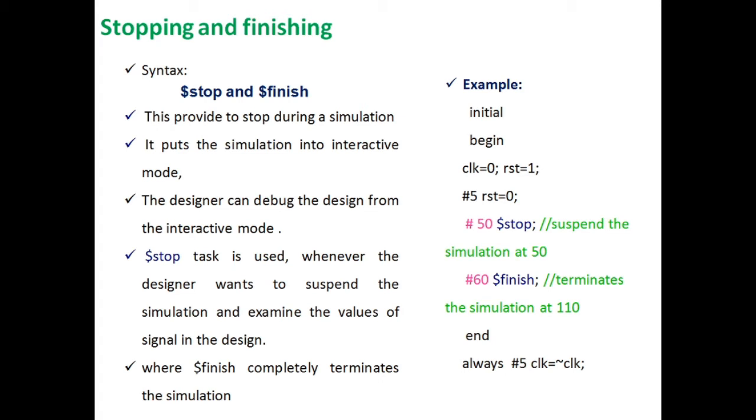$stop. But the purpose of $finish is that I am completely terminating the simulation. So that is the difference between $stop and $finish. Let us again move back to our Xilinx tool. Okay, here I have written some example code. Clock equal to 0, reset equal to 1. After 5 seconds, reset is equal to 0.